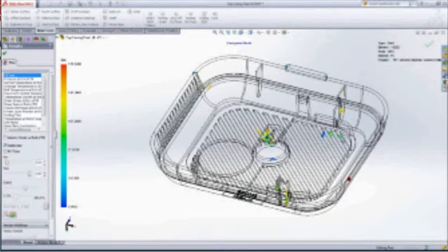The new injection location definitely helps us reduce significantly the weld lines, and we now pretty much don't have weld lines on those ribs.